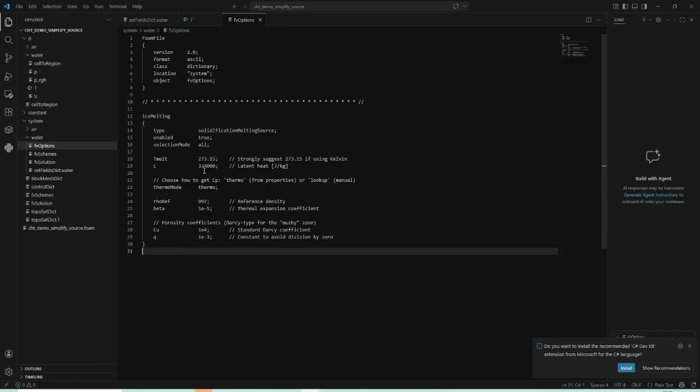So that is the source item, allowing you to define that in OpenFOAM. And there are several main items. So the melting point is the phase change temperature for the water. We know it's 0 degrees, right? I use 273.15 because I use Kelvin, and the latent heat of water, or of ice, is defined here, and also we use the heat capacity from thermo because I have the thermo defined by the constant properties.